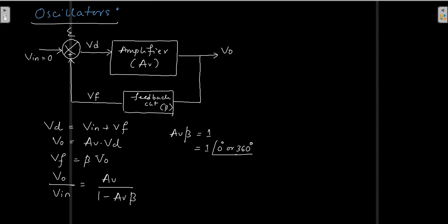Now you can say that we are in a position to have self-sustained oscillations, provided your feedback circuit supports that, right? Suppose you have an amplifier. When I speak about the amplifier, definitely your gain will be 1 or more than that. One condition gets satisfied, and the second condition, the phase shift should be either 0 or 360 degree as per Barkhausen's criteria.